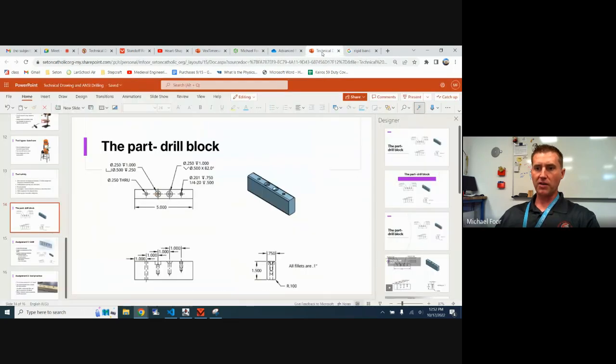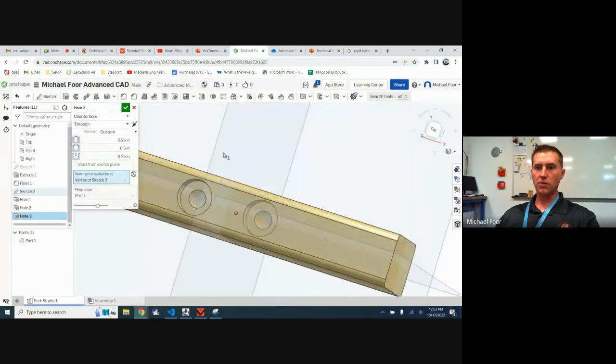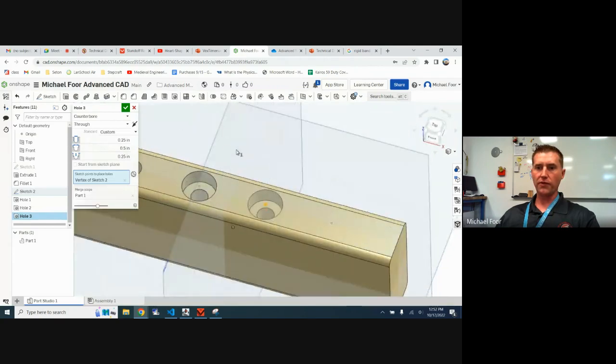And if we look back here, this is a countersink hole, or countersunk. Okay, it's a 1/4 inch drill bit that goes down 1 inch. Okay, it's a 0.5 inch countersink at 82 degrees. So, oops, I think I actually went through on that. We'll fix that in a second.